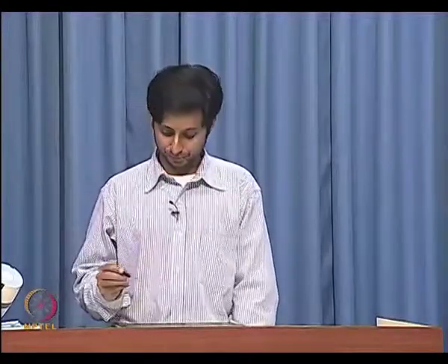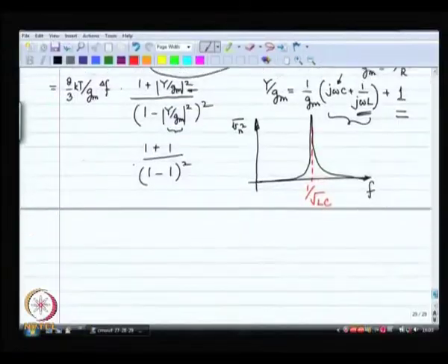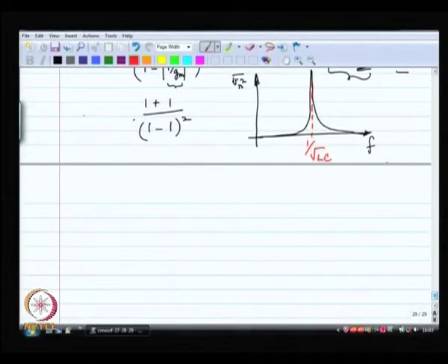That was a question raised in the previous lecture, right. I mean the question was, if at all it oscillates, what will be its amplitude? Why not 0 amplitude? So, this is why it will not oscillate with 0 amplitude. It will oscillate with significantly large amounts of amplitude, even when r prime is exactly equal to 1 by GM. You will get perfect sinusoid oscillations, but because of noise.